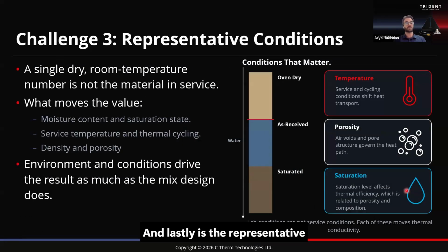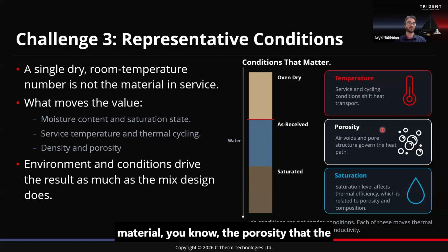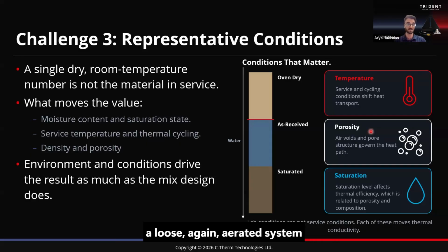And lastly is the representative conditions. So I would say for thermal analysis, your environment is going to be a factor in any application. But of course, here we could look at a few standouts: the temperature at which you're testing the material, and the porosity of the material. Like, in your preparation or sample formation, are you going to be densifying the sample, or is it more of a loose, aerated system? And the temperature as well as the saturation levels will, of course, have an impact related to some of these other factors as well.